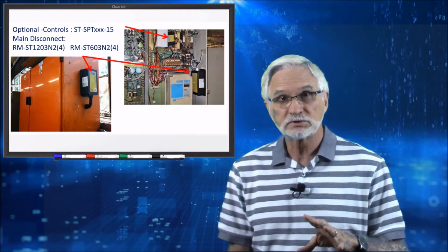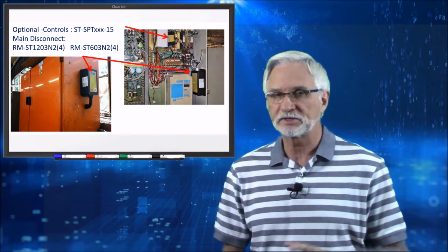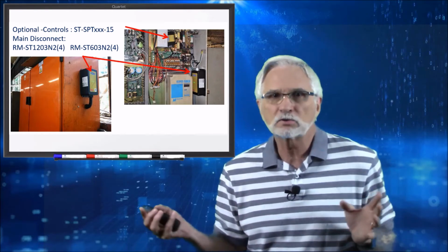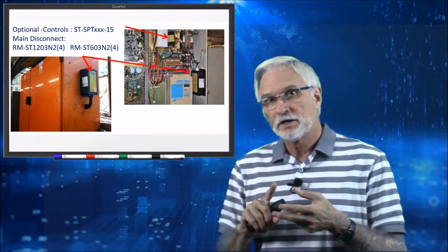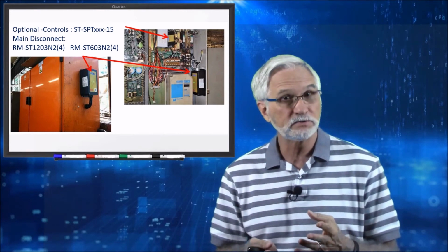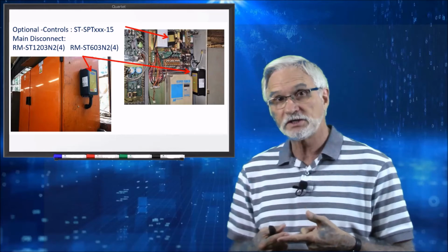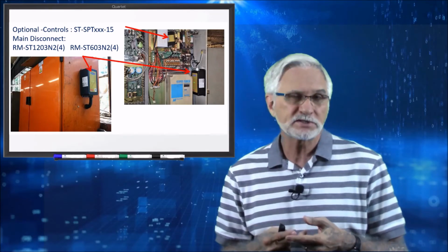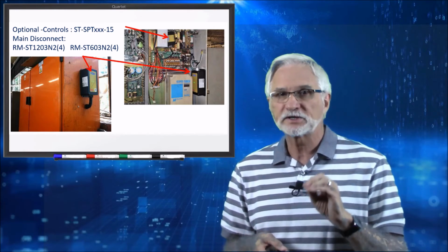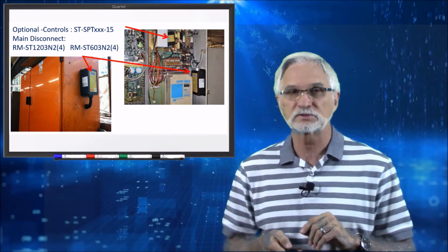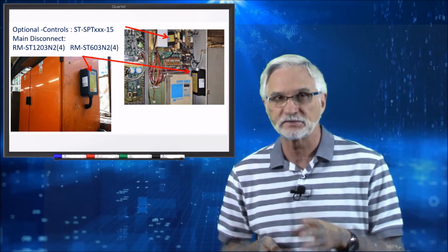CNC machine tools, tremendous application. We have applications for manufacturers from all across the world. It's possible to get by with 1 unit. We always prefer 2. So then you're looking at the RMST 60 or 40, maybe an RMST 120, and then find out what that control voltage is. So to protect that, the most critical nerve center of the CNC itself.